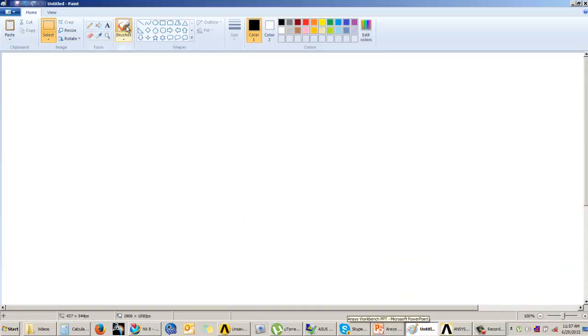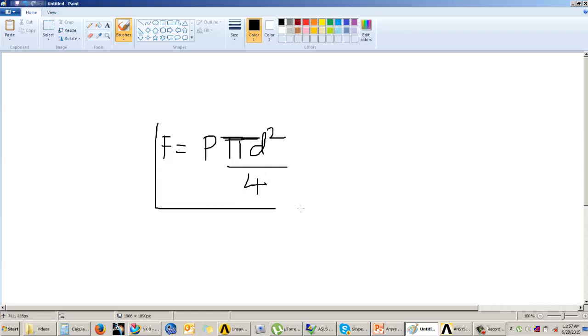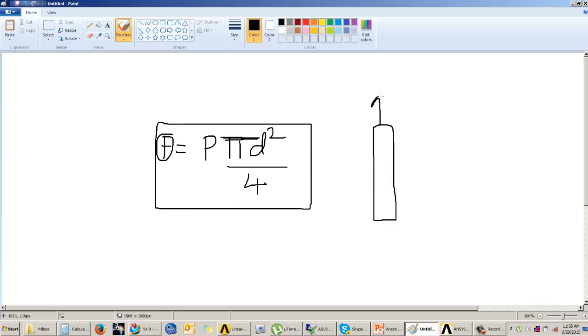Because it is going to be closed from both the sides, we will have to apply a force, and we will calculate this force based on the pressure and the area of the circle. So this is the formula to calculate this force, which will act on the pressure vessel from the top, just to create the closed section condition.